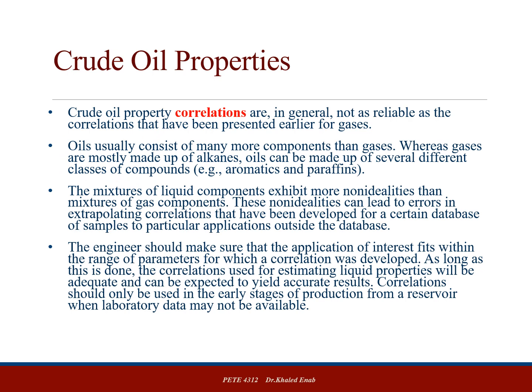Crude oil properties are different from gas properties. For gases, there are reliable correlations with a small error, and there is also a kind of perfect ideality for the gas when it's under low pressure and high temperatures.